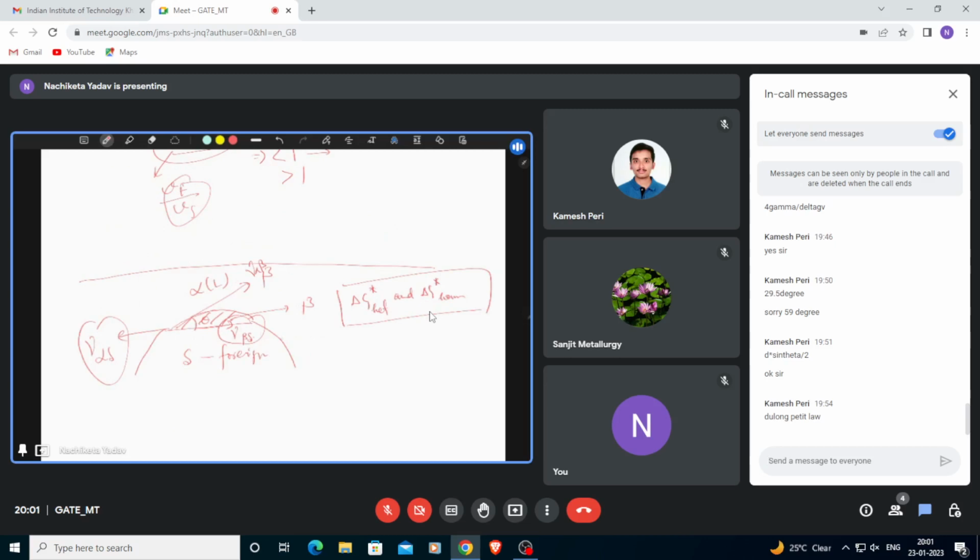From the energy balance you can calculate gamma alpha delta equal to gamma beta delta plus gamma alpha beta cos theta, and here we know delta G heterogeneous equal to 1 by 4 delta G homogeneous, (2 minus 3 cos theta plus cos cube theta). It is a function of theta value.